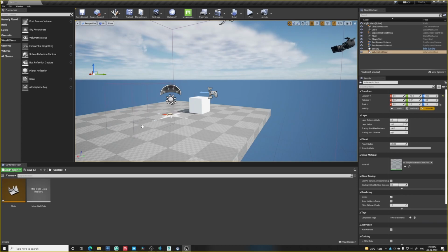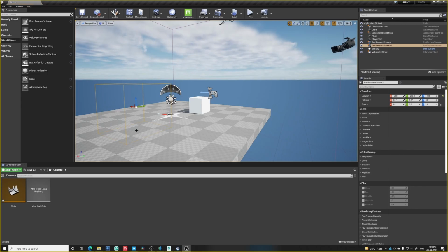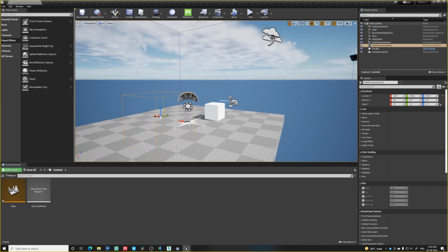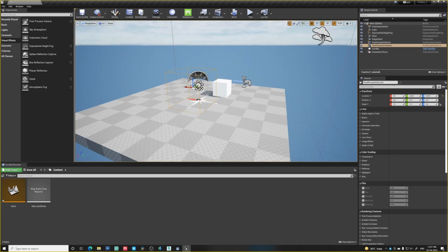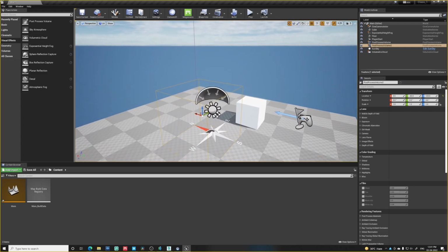It's simple, actually. You just use exposure, brightness, contrast, hue, saturation. Like in Corona Render, you do it at the end: you add the bloom, you use the grade part, hue, saturation, brightness, contrast. For that, you can use this post process volume.